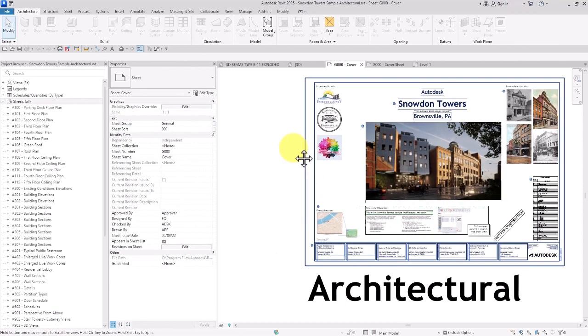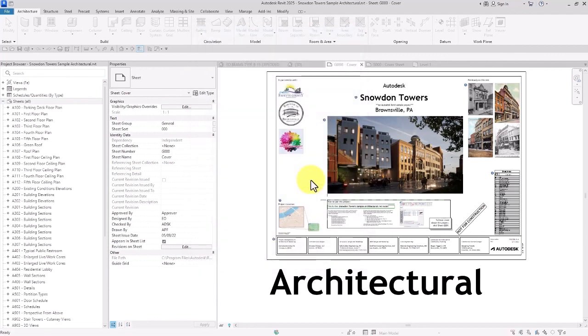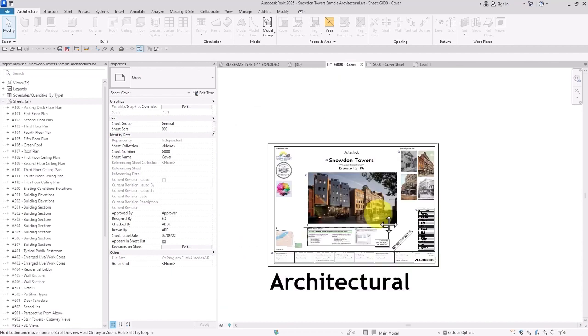And now let's see how it's done in Revit 2025. As I said before, I'm going to activate export in background. Then try to export the files again. The software would be unavailable only for a few seconds while the process is being started. And after those few seconds, we would have full access to our software again, and we won't face any limitations while the process is on. Then we can check the process down here in background process as well. Just wait for it. Alright, now the process is started.